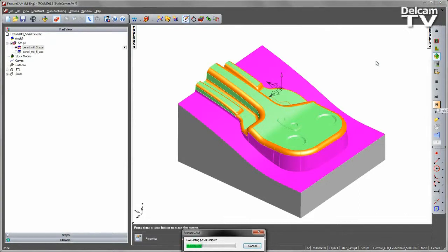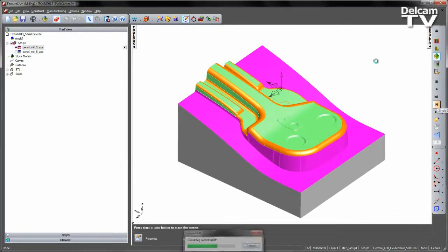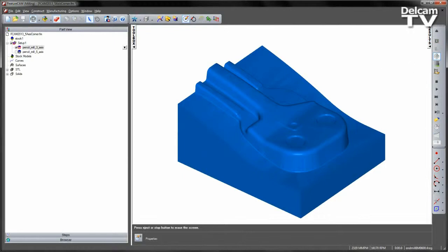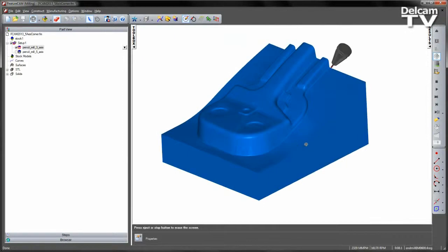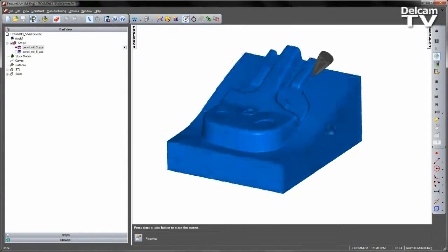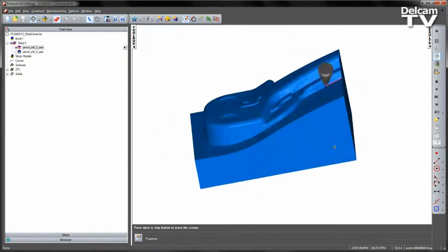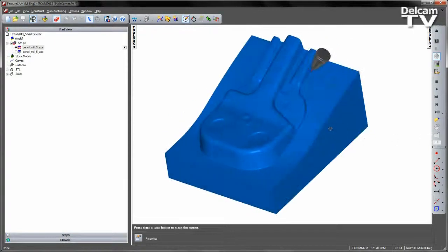We get the same calculation, only this time we're going to add a 5-axis orientation. The tool comes into position. Again, single step or using Alt F3. You can now see the tool is already tilting into position. I can now let it flow through, and you can see the tool is tilted over and is now collision free.